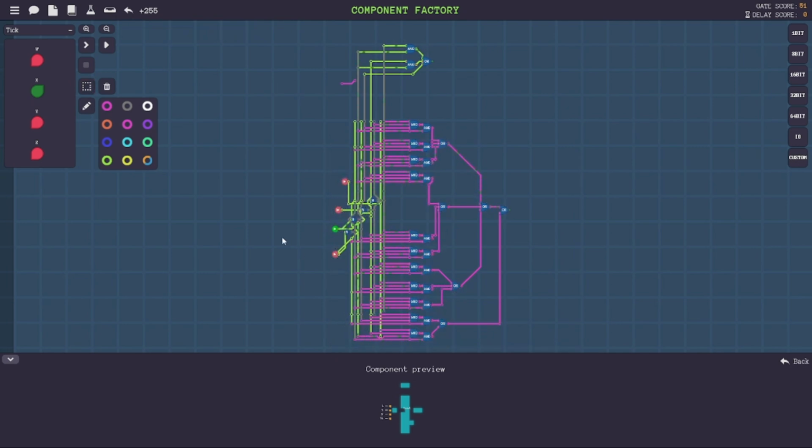That's why we use either Boolean algebra to simplify the Boolean expression, or we use Kmaps or other methods to simplify it. First, we will have fewer gates, so the cost will be less and the circuit will be easier to implement. Also, the performance will be much better, because you see the delay will be much less. The signal has to travel through fewer gates, so it travels faster, and that means better performance. That is just a simple example.